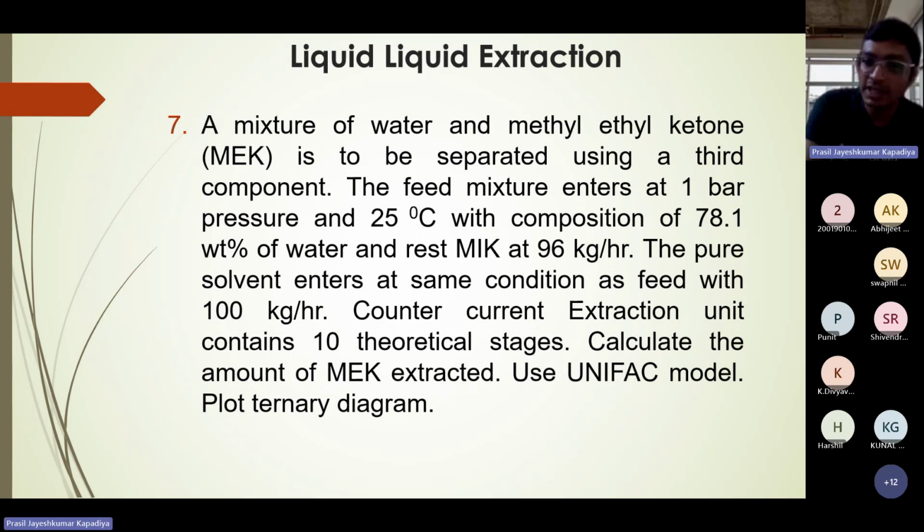The solvent is N-octanol. I have not mentioned it here. The pure solvent N-octanol enters at the same condition as feed with 100 kg per hour. Countercurrent extraction unit contains 10 theoretical stages. Calculate the amount of MEK extracted. Use Unifac model. Plot ternary diagram.